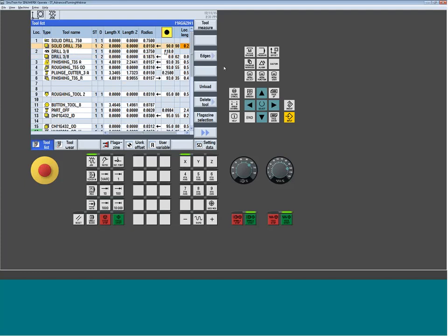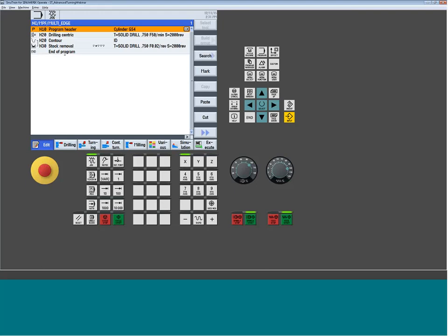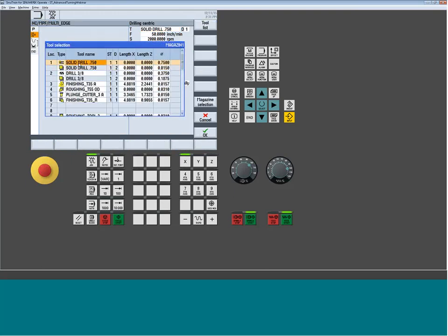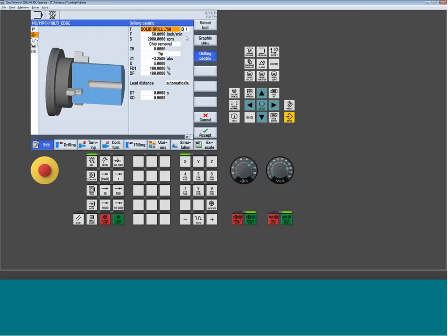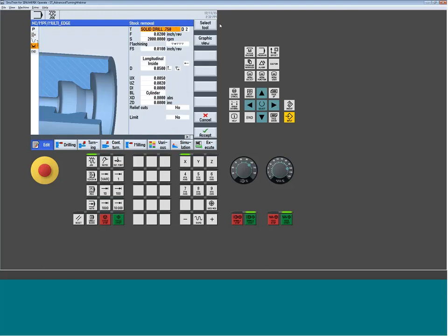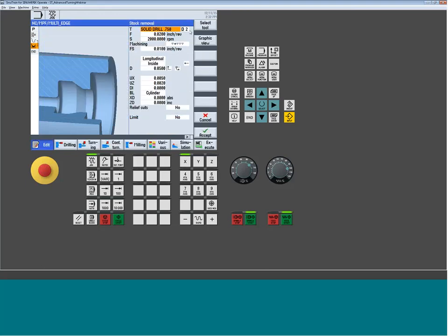Now when it's time to physically use the tool, here we have a quick little ID program. So first logical thing would be drill a hole, right? So I'm going to go in, and I'm going to select to drill a hole. And the big thing here is I just want to make sure I pick the appropriate cutting edge, because the cutting edge, when I select it, is what's going to go and fill out this D number. And a lot of us kind of never paid attention to the D number because I was only ever making one cutting edge. But once I get to, let's say, the ID turning operation, and I go select the next one down, it automatically fills out the cutting edge to be number 2.